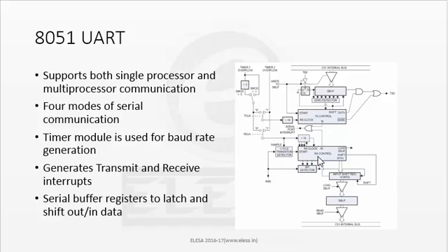The RX control block initializes the input shift register with a value of 1FFH. This is a 9-bit data wherein the use of the ninth bit can be avoided.